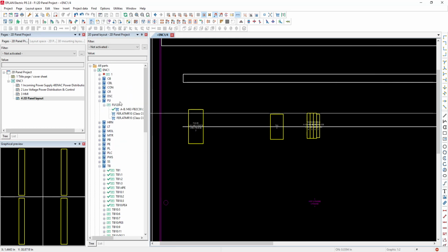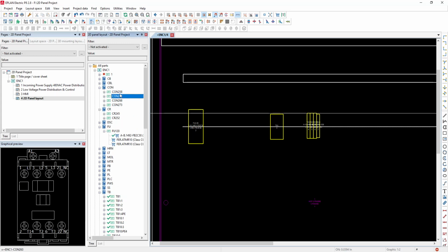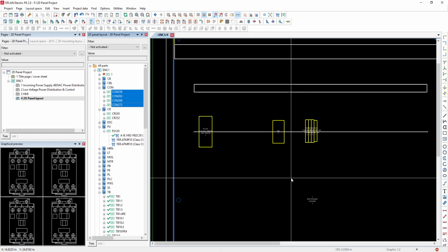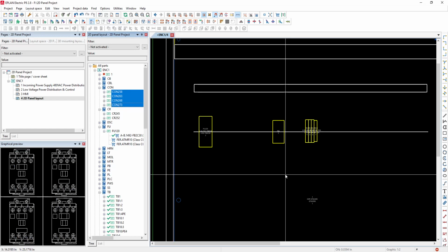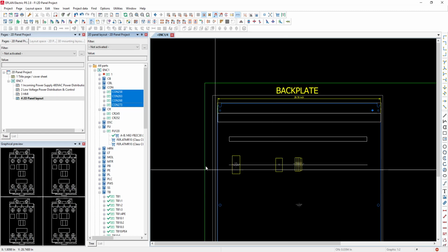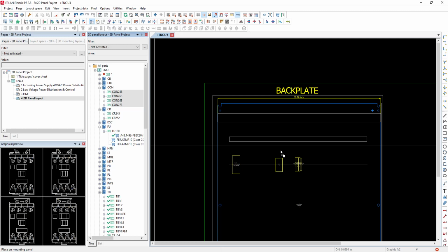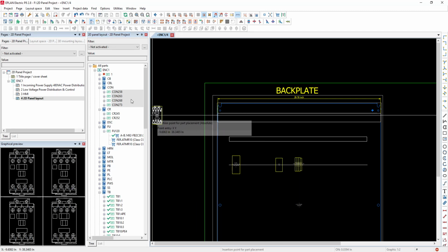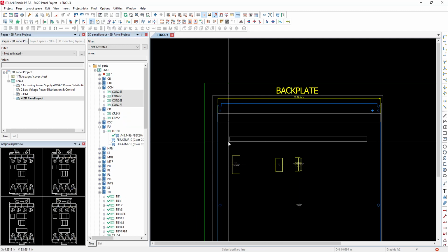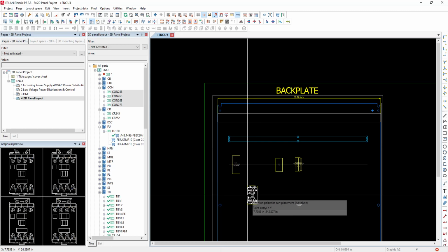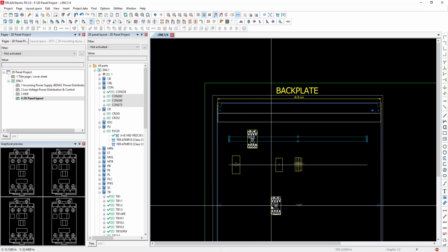In the case of components, if I actually grab some components like this one here, these ones do have a little macro, so it's up to you to assign the macro. Some of these things are available on the data portal. Some you might have to do. So basically, again, DXF, DWGs and bring them in. You can drag and drop it out, or I can actually say here, place on mounting rail, select my rail, and then just start placing them, click, click, and click.